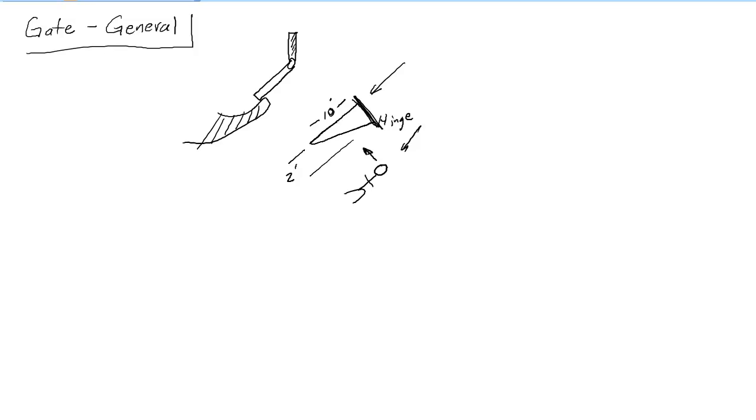Now what you notice is if you take a little dy here and you look at the d area, as this area gets smaller, the d force that comes from it is gamma times h. That's the pressure, or I could just go with pressure times d area, but we already know that the pressure is gamma h.